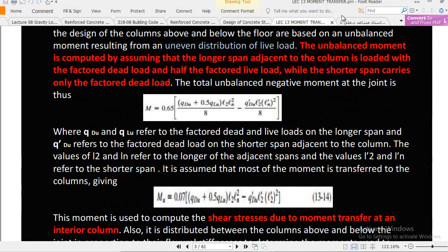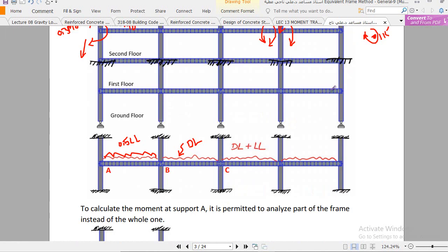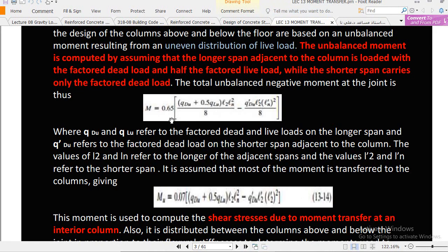you see that in the case of the direct design method, when you have a flat slab system, the lateral distribution coefficient for the moment at this interior face and at this interior face is 0.65, and for the mid it is 0.35. Now this is the 0.65 which you see here, right? This one is that coefficient.